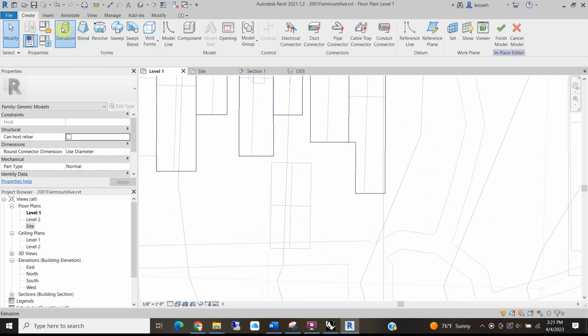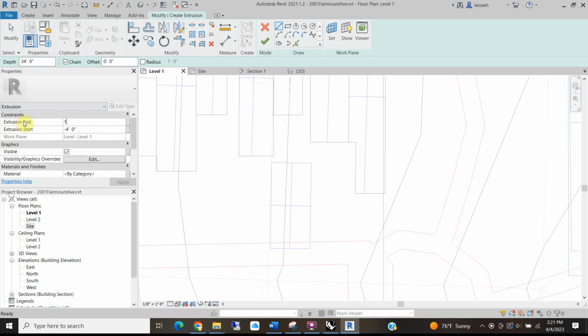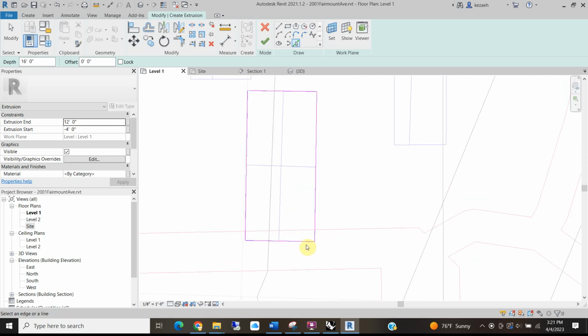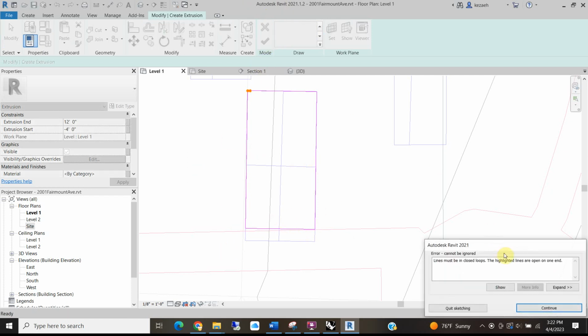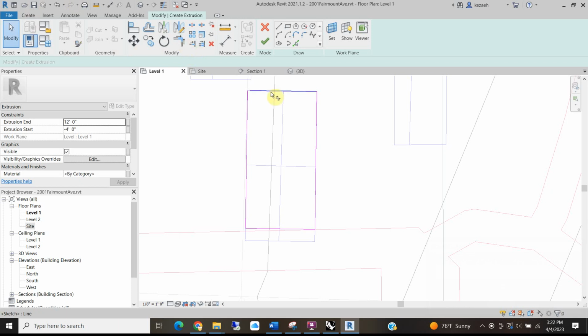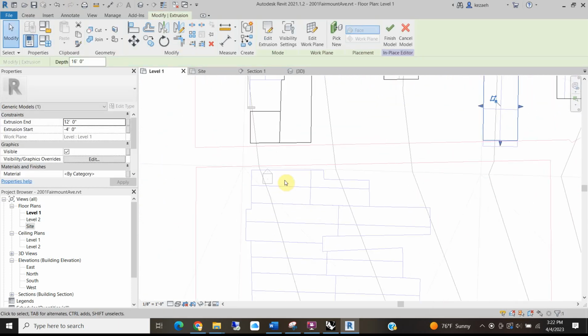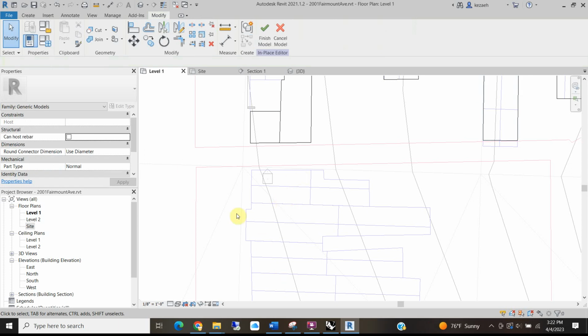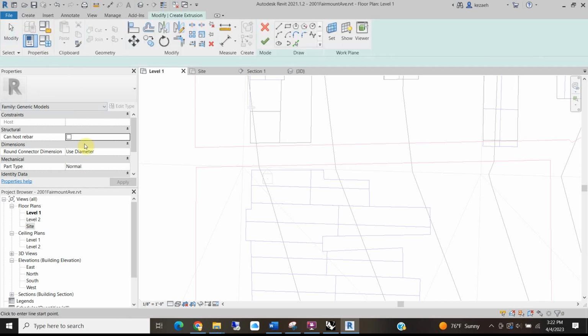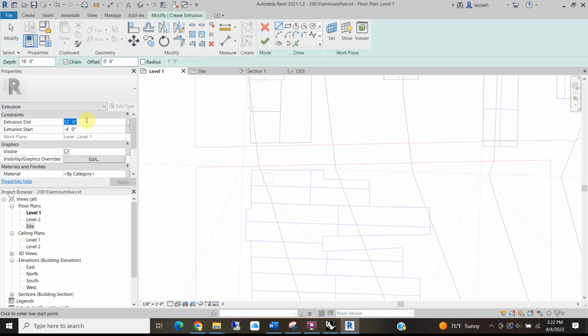So I'm going to create extrusion, but this one will also be only 12 feet tall. I'm going to just bring this back off the road. I don't know if the road is wrong or the building's wrong, but I'm just going to make it so they don't intersect. And that corner I have to finish off with the trim extend tool. Okay, and then also we might need some buildings back here that might show up. So creating extrusions for those, and again, those should be 30 feet.